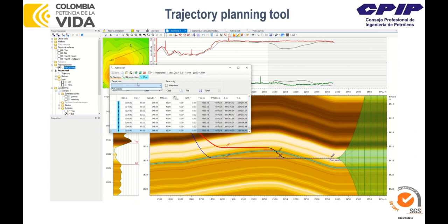Okay, so what if I try to do it in the automatic mode, plan survey, and now I put my dogleg as 0.1. Okay, and I do build, and I do save. And you see now it's a different picture, right? So it took longer for the trajectory to get back to this point. Or if I put, for example, very aggressive, like 1, build and save, and you see it's almost immediate.